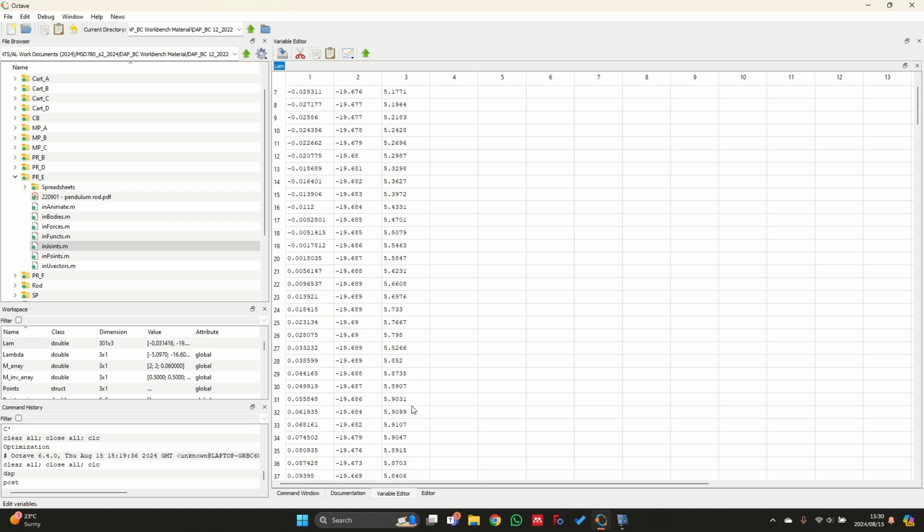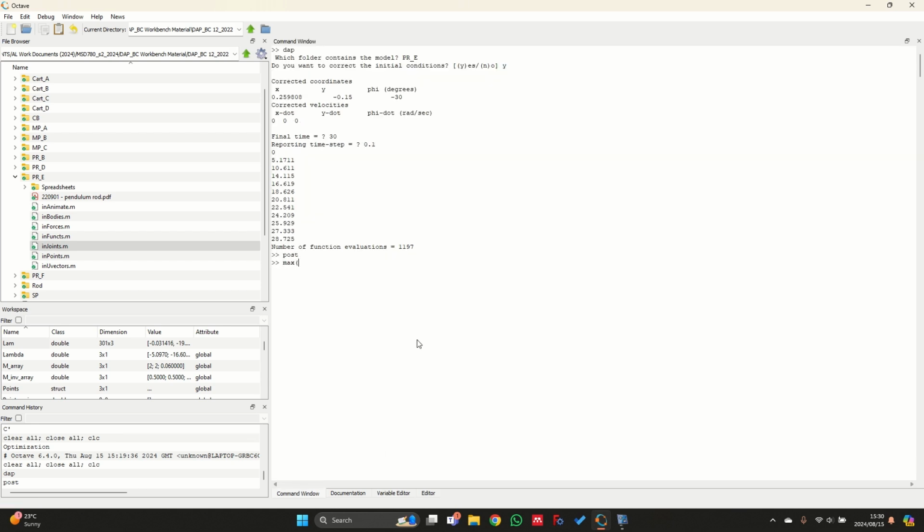And if I'm perhaps interested in what the maximum value is, we can see that it's about 5.9, but I can also go and just say max LAM. I'm going to test it over all the time points just for Lagrange multiplier 3. And I can see the value is about 5.9111 that I get over there. So that's then in Newton meters. Since it's a positive value, it means that it's in the counterclockwise direction. So by specifying the relative rotation driver, which induces a 2 pi over 60 radians per second squared acceleration, the resulting Lagrange multiplier, which is then the torque, is going to be 5.9111 Newton meters counterclockwise.